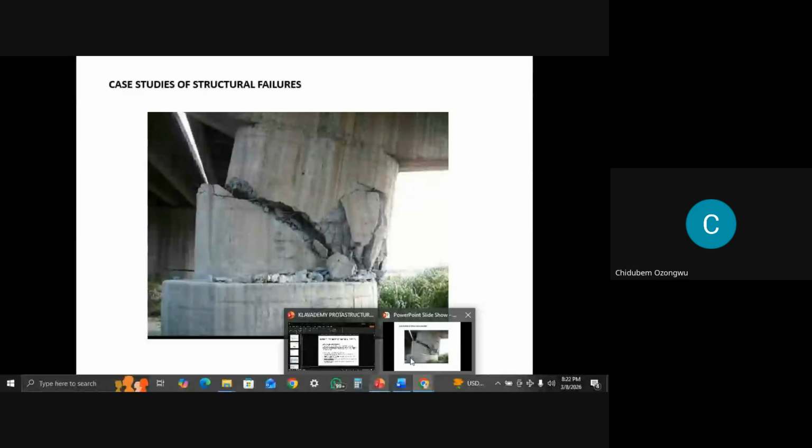But if it is only this column that has an issue, and there is no other column that has an issue, I think it is still possible to use jacks, because in that building we worked on, you can still hold the other two sides with a rolling jack, with tiny spaces, and then work on this column and decrease the spacing of the stirrups, like Mr. Godswill said, because I think that's what caused the shear.